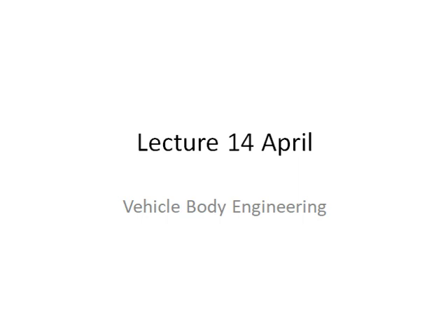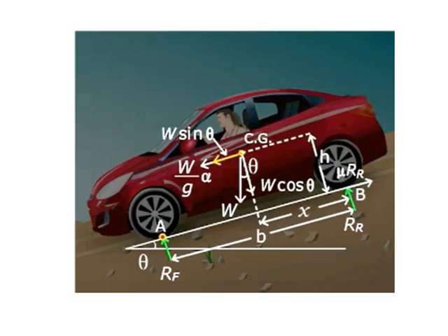So it's very critical to calculate the load distribution of the vehicle before the braking, after the braking, or before the acceleration, after the acceleration. We had seen during some calculations and derivations the expressions for finding the load transfer or the weight transfer during braking, and similar concepts can be applied for acceleration also. So let us quickly see that.